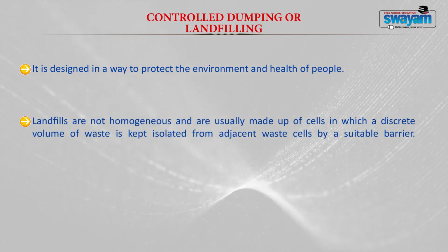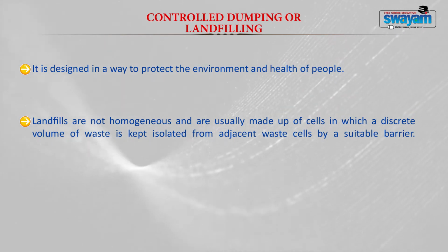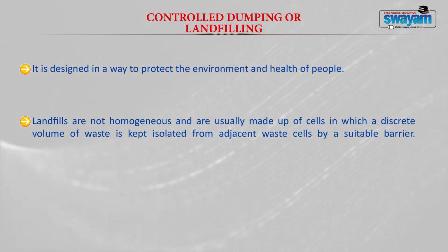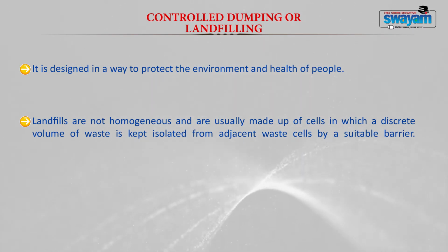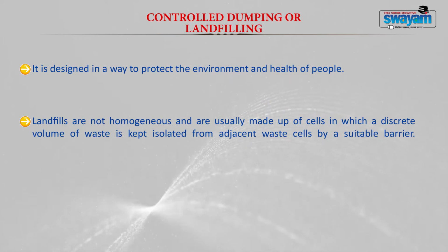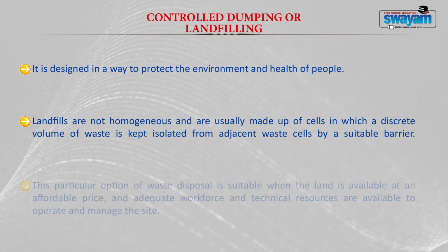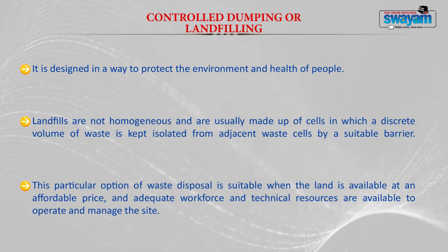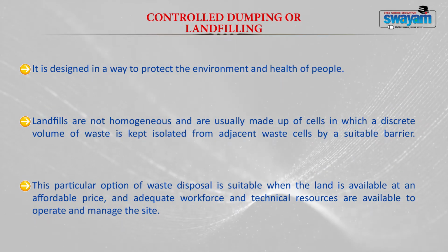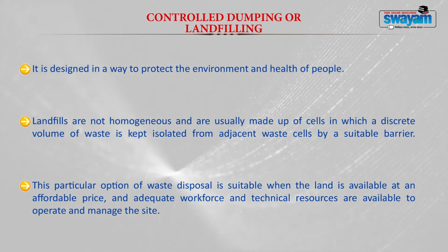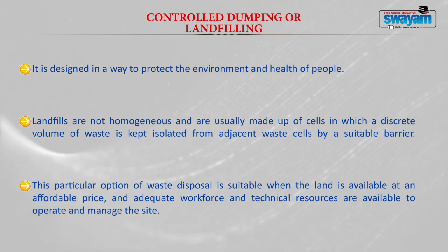Now, landfills are not homogeneous, they are usually made up of cells. As I mentioned earlier, here the waste is loaded in a systematic manner. It is not haphazardly placed, nor homogeneous. The waste is placed in cells where a discrete volume of waste is kept isolated from the adjacent waste cells by a suitable barrier. This particular option of waste disposal is suitable only when land is available at an affordable price, and you have an adequate workforce and technical resources. If these three things are available, then you can go for a landfill option.